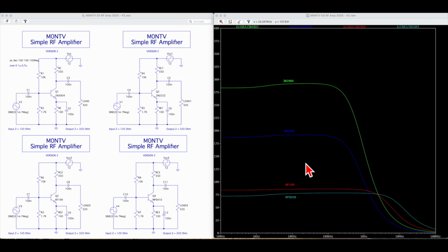And whilst you can, of course, use any transistor you want, and of course you can use these, you're going to have to accept some shortfalls, and pretty steep shortfalls if you're going to do this. And actually, this will be compounded in the next video when we talk about another of the challenges. Effectively, by using the 2N3904, we're using something that it wasn't designed to be doing. Now, that's not to say we shouldn't do it. It's of course possible, but that adds a layer of complexity if we are to design it and to build it correctly. So it's a bit of a trade-off.